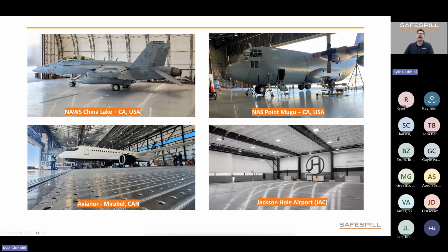In comparison to that, again, on the commercial side, we did a wall-to-wall application at Jackson Hole Airport. And this is actually an FBO facility, but they do have 1 hangar bay where they do maintenance operations. And so we installed ILDFA in that hangar bay. This is wall-to-wall, so it provides flexibility for parking configurations. Various aircraft are coming in. And so because of those potential unknowns, it was best to cover the maximum extent of the hangar and provide the most flexibility for this facility.